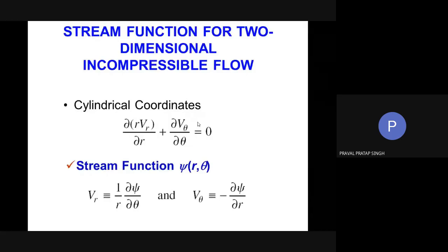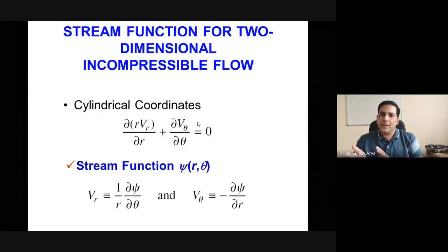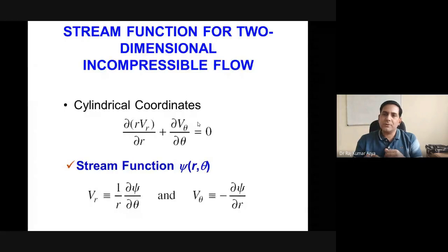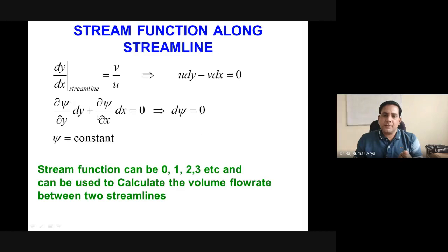Okay, sir. Done. So you got your LHS equal to the RHS, right? In terms of the stream function also. So you can say that the stream function satisfies the continuity. Fine. Yes, sir. Now we are going ahead from there, to see what the stream function value would be along a particular streamline.